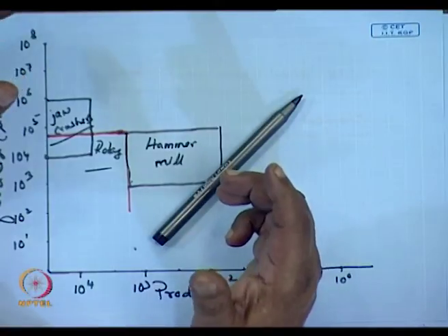Now, the plus point that we have is that most are made up of iron. So, frequently the best way to remove these iron impurities is magnetic separation. As the powder comes out, have it run through a magnetic field where the iron particles are segregated out. In any of these crushing operations, as I said, contamination is a major problem and one has to take care of that.